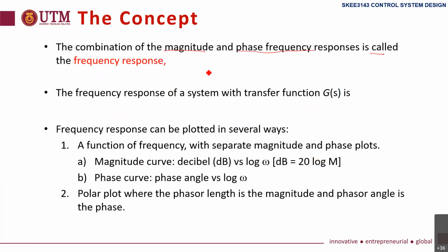Usually we write M in terms of omega and also phi in terms of omega. This is the frequency response. Usually we present it in a graphical representation. Later, one of the techniques is using Bode plot to represent the frequency response of the system.